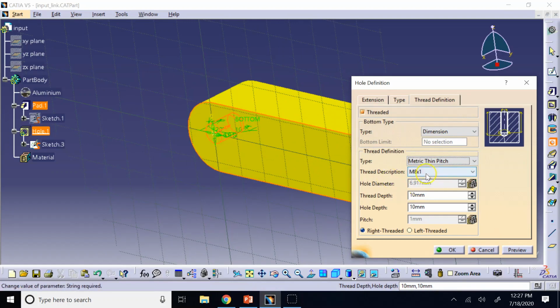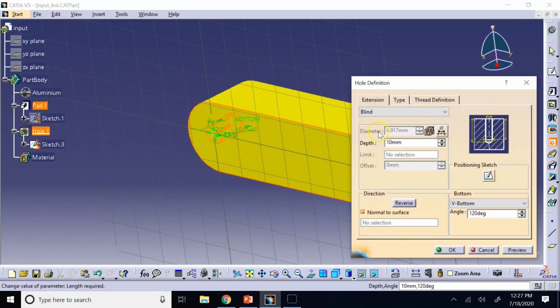Of course, you cannot have 8. That's another thing. If your hole is 8, your thread major diameter cannot be 8. It has to be bigger than 8, right? You cannot drill a size 8 into something and then use a bolt with diameter 8 in it, because you always need to leave a little bit of room to cut the threads inside the object, to tap the object.